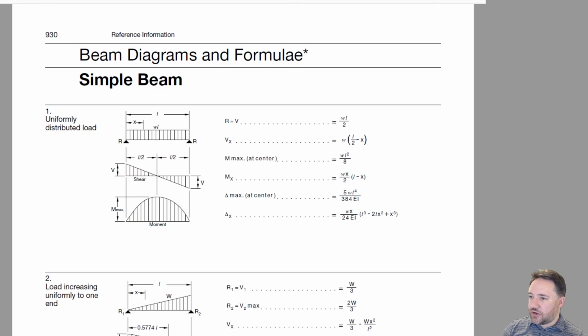But also there are the regular beam diagrams and formulae. So for example, for a simply supported beam with a uniform dead load, you can see here it provides a calculation for the deflection at the center. And you probably recognize this equation, 5wL^4 over 384EI, for a simply supported beam with a uniform load, and they have beams with cantilevers, and they have beams with multiple spans.